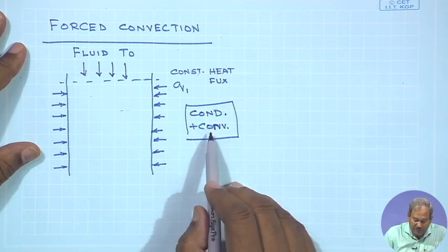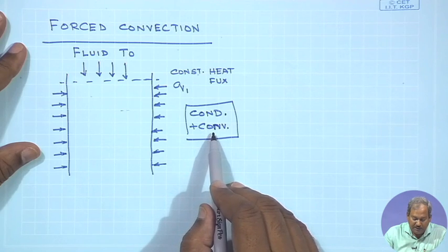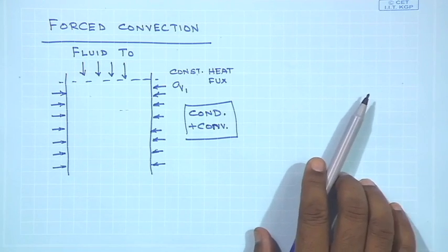Now, whenever you have convection present in the system, you are dealing with a velocity of the fluid. The convection is induced by the velocity of the fluid, and we understand that when a fluid flows in a pipe under the action of gravity as well as an imposed pressure gradient, in laminar flow the velocity profile that you would expect is going to be parabolic in nature, which we did in our treatment of fluid mechanics, momentum transfer.